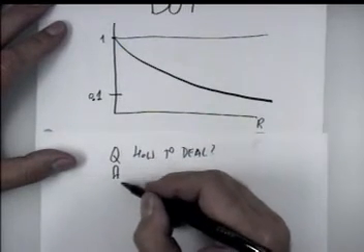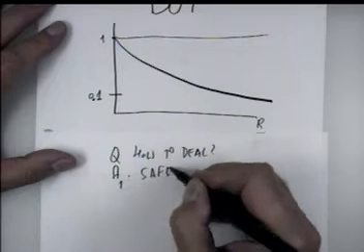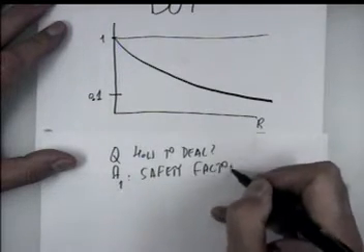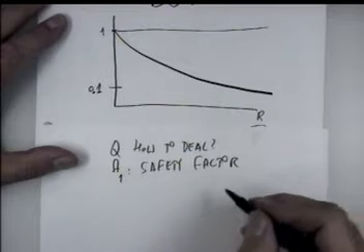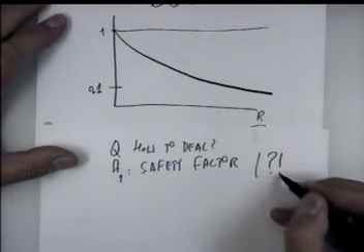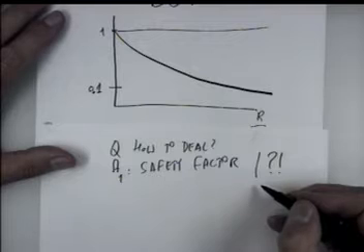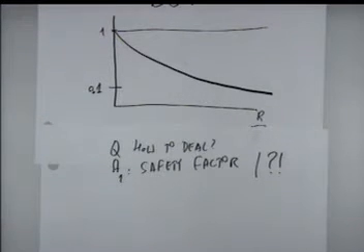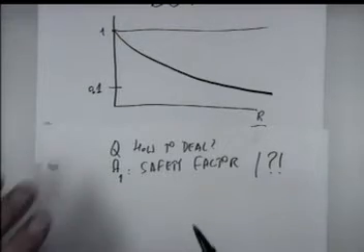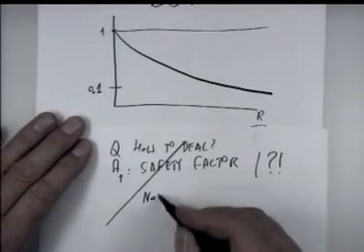Question and answer of person 1, safety factor. But look, please, safety factor, actually I will put here a question mark and an exclamation mark, because how much safety factor will you take? 2? If you take a safety factor of 2 it is not helpful, because the theoretical value says something, you divide it by 2, but in experiment it buckles 10 times less. So no one is going to take a safety factor of 10 or 15 or something like that. So safety factor is not helpful.